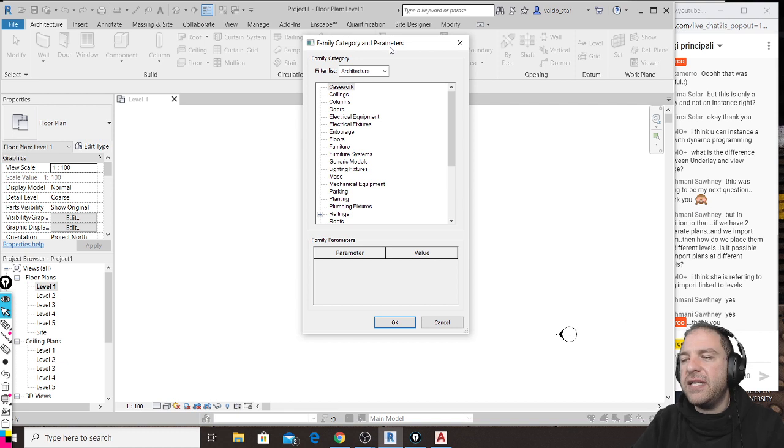First thing that you need to do in Revit is let Revit understand which kind of object you are about to create. This is extremely important because according to the object that you create, Revit will assign certain behaviors to your object. Just to make 3 examples.